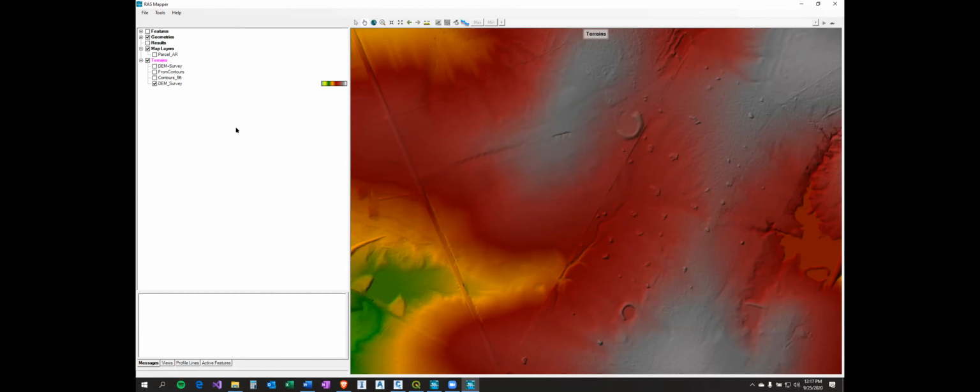The only thing I've had a problem with is that a lot of times the data downloaded from TNRIS, the vertical rasters might be in meters, and you just need to pay attention to that. A survey vertical raster from Civil 3D might be in feet, but the vertical rasters from TNRIS might be in meters. So you might need to do an intermediate surface to make sure everything is in US survey feet. Yes, I typically have to prepare this data for people doing HEC-RAS, and that's why I was asking.